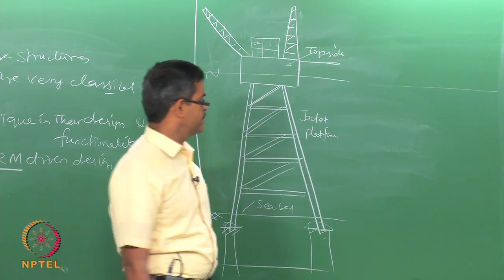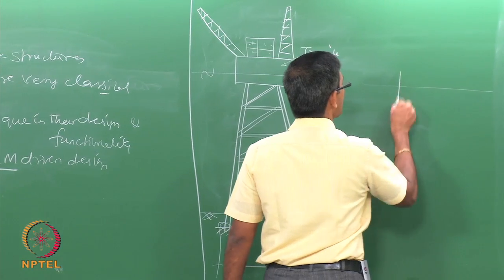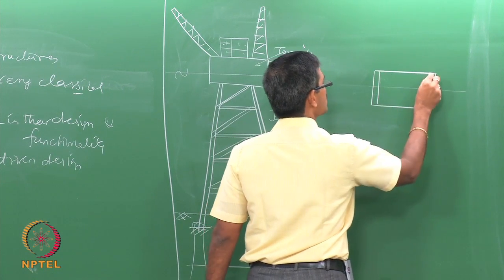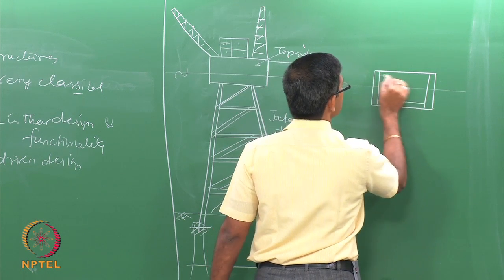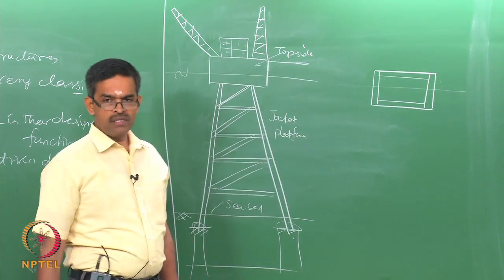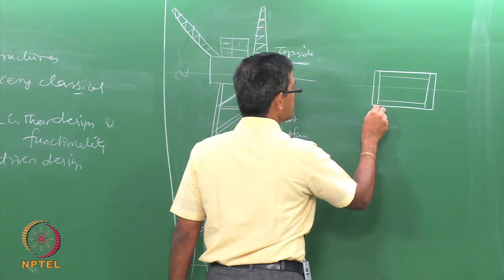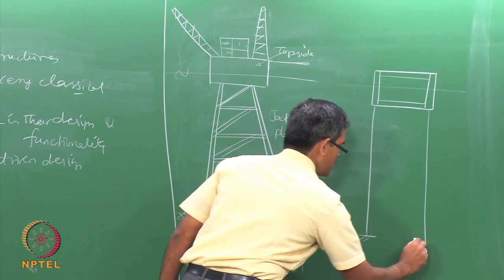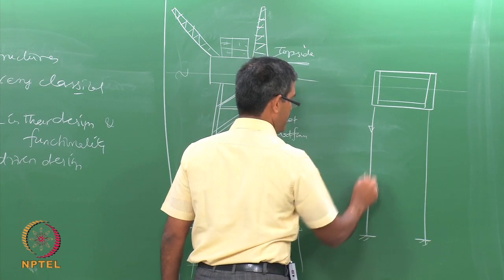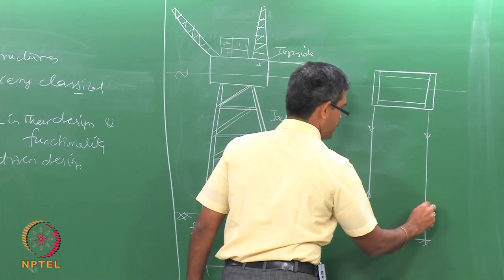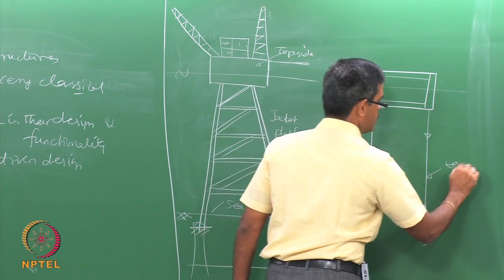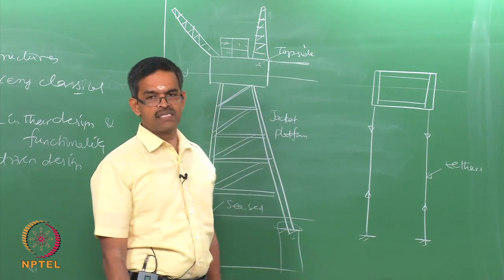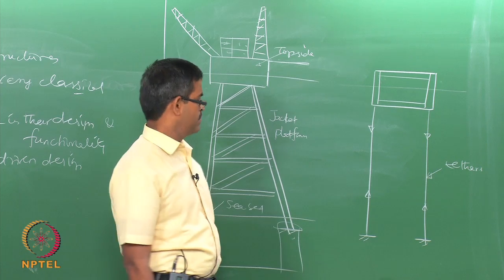and production, we have a typical platform called a tension leg platform, which has vertical columns and horizontal members, which are pontoons, which are actually supported to the seabed only by tethers, what we call tendons or simply axially stressed cables.